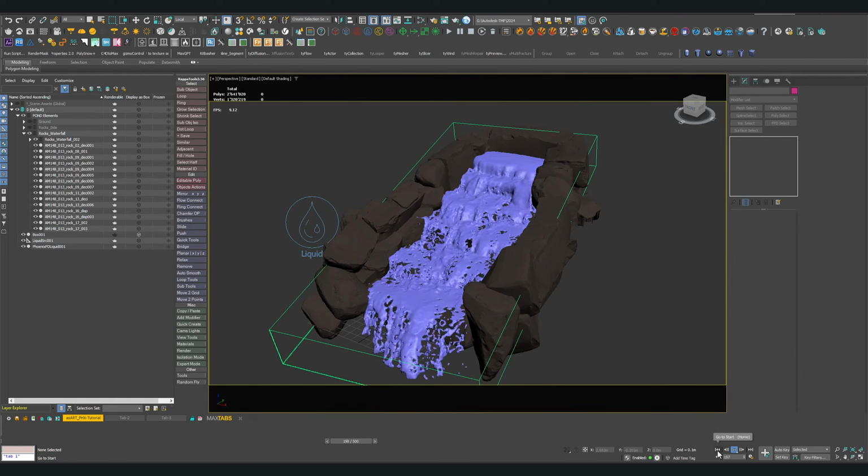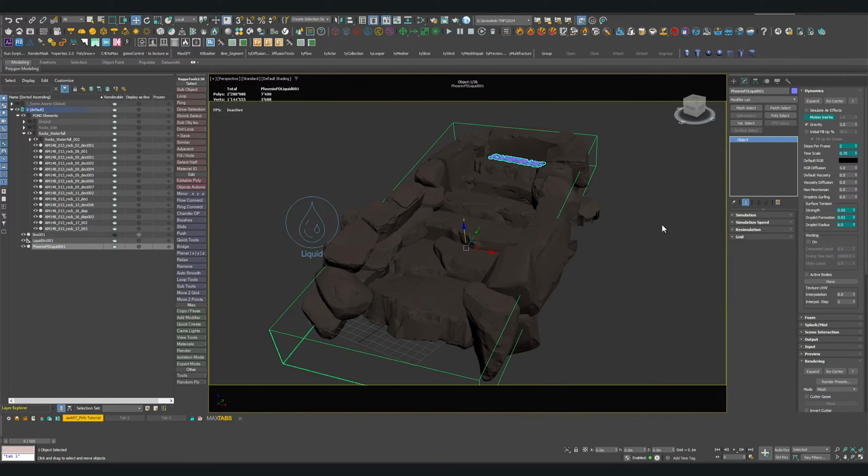So for this, I'm going to change that formation here to 0.05 and see if that will help. And I'm going to actually reduce the droplet radius back to 3, so we don't have those big droplets. So let me go and delete the cache and resimulate it.